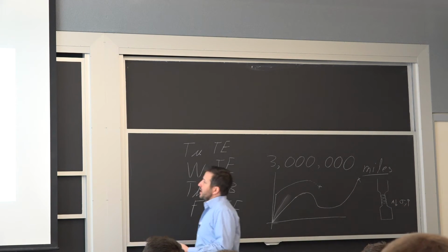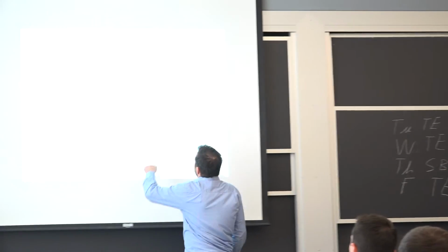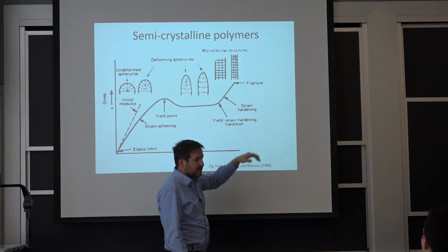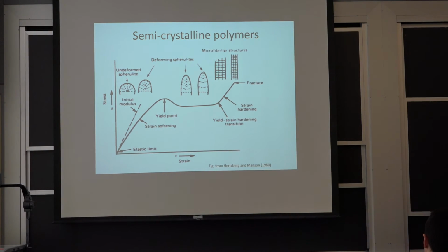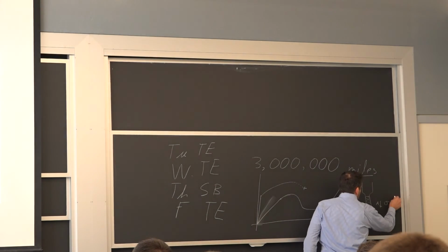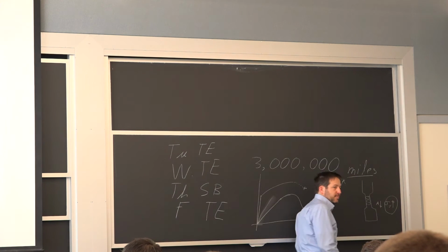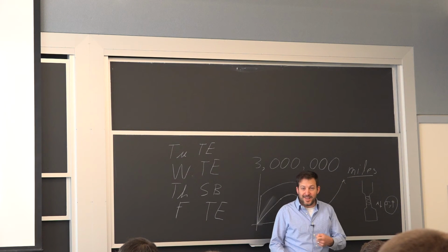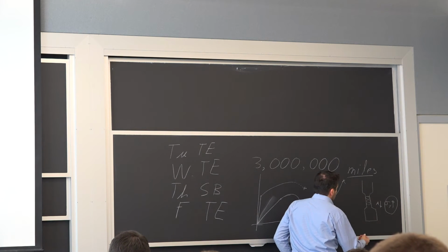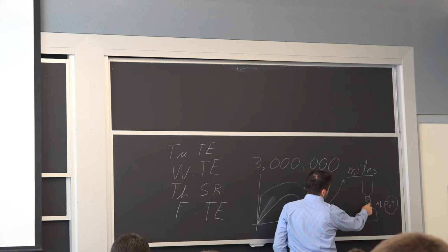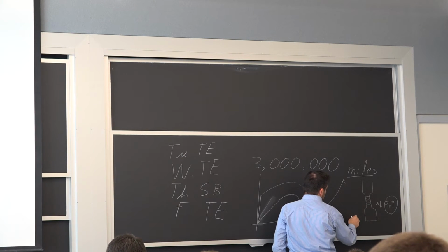But because you have this fibrillar structure that's starting to take place, there's just so much strain hardening that you reach that point where this is going up through the roof, becomes a lot more rigid, and that neck stops. So what happens in deforming a polymer in tension is you can have the neck formation, so your specimen's going to look, if we just draw this section, literally look like this.